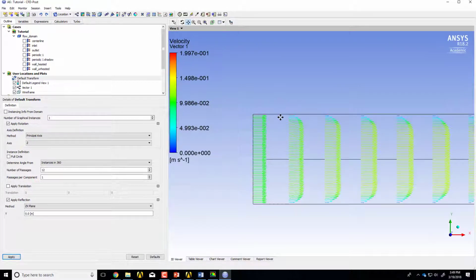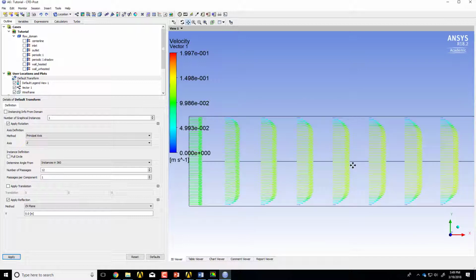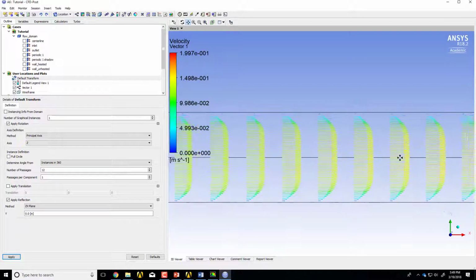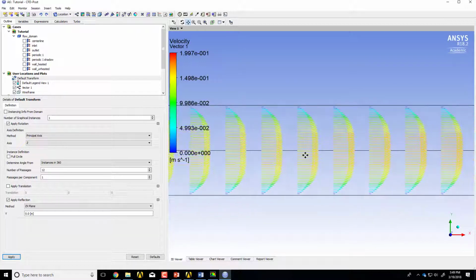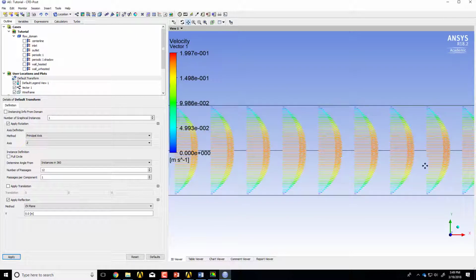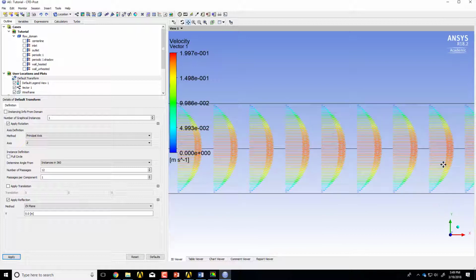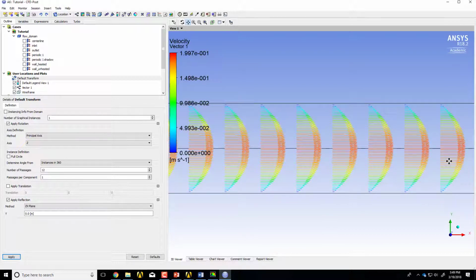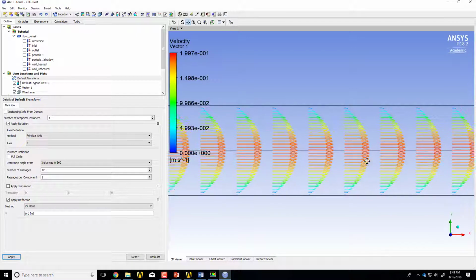So that's like a cross section through the pipe, and now I can see how the uniform velocity profile is evolving into the expected parabolic profile. So you can see the velocity profile is still evolving, and somewhere down the line you are beginning to see fully developed flow. And all these are coming from the cell center values based on interpolation.